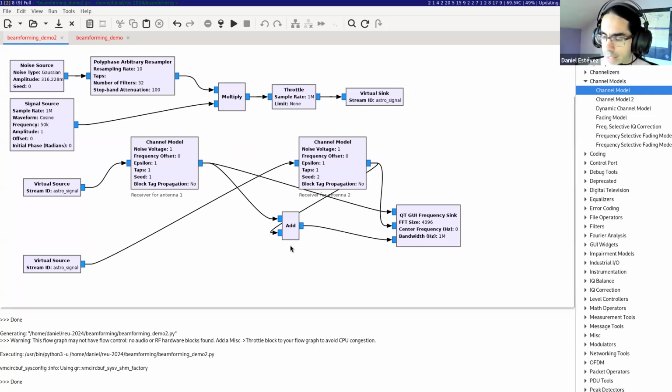So I cannot really add these two signals together without compensating for this delay, because I will have unwanted effects. I think that is quite clear. The source can be anywhere on the sky, and usually the length that the signal travels to reach one of the two antennas will be different from the other. That's one reason for a difference in delay, and that's what is called geometric delay.